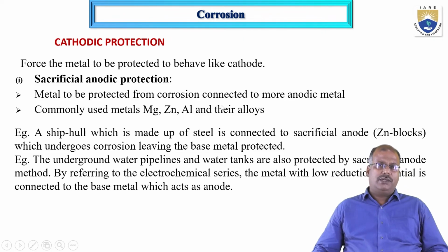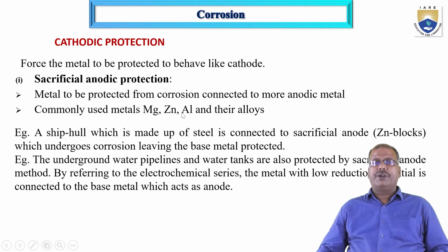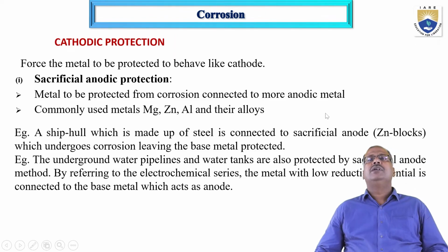Okay, all the corrosion happens with the auxiliary anode, which is more reactive than the steel, which contains iron. So from the word itself, it is a sacrificial anode. The anode you use will undergo oxidation, and metal structures like steel structures are prevented from corrosion.